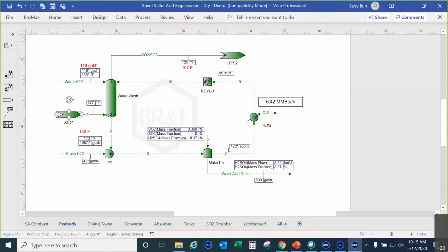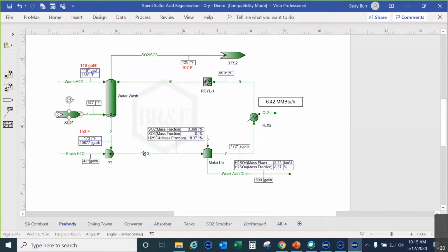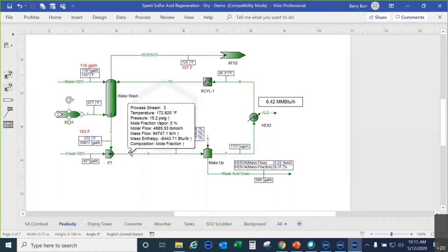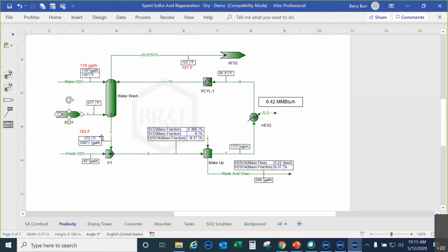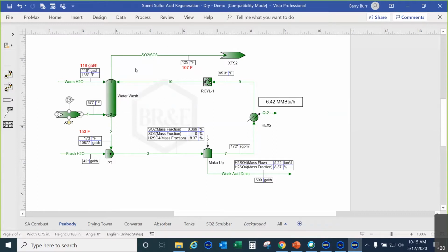And it's not an electrolytic model, it's a pure component model. There's no ionization that's occurring. So if you're used to how we treat amine solutions, that would be an ionic package, and you would see a breakdown of species based on their ions, but you won't see that here with an NRTL-based thermodynamics package. But you see here we have the inlet gas coming in at 577 degrees, and we're cooling it so that it exits at 125 degrees.